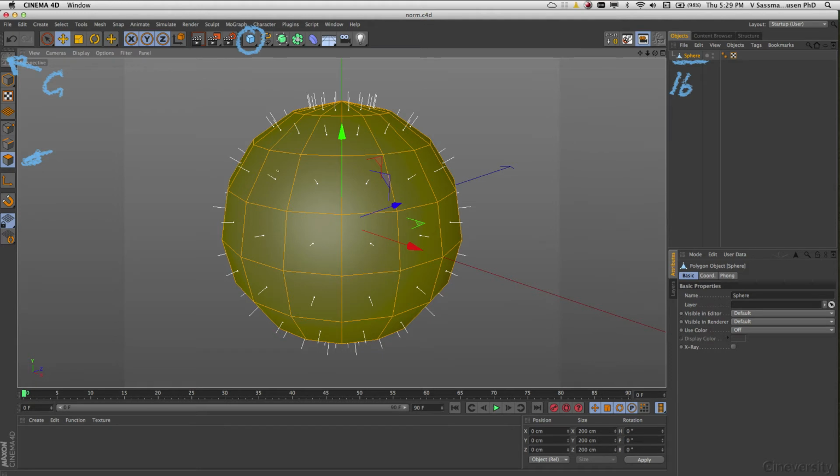And you might think, I don't have here these white little pins on it. These are normals, and the normals are very important for the calculation of the surface. You have to go here in this menu and configure all to get the normals, the tinted ones, and then you have these little guys. They have no influence to your final result in terms of rendering, but they are there in the calculation, and they create finally what makes this whole sphere smooth instead of just facet-like.